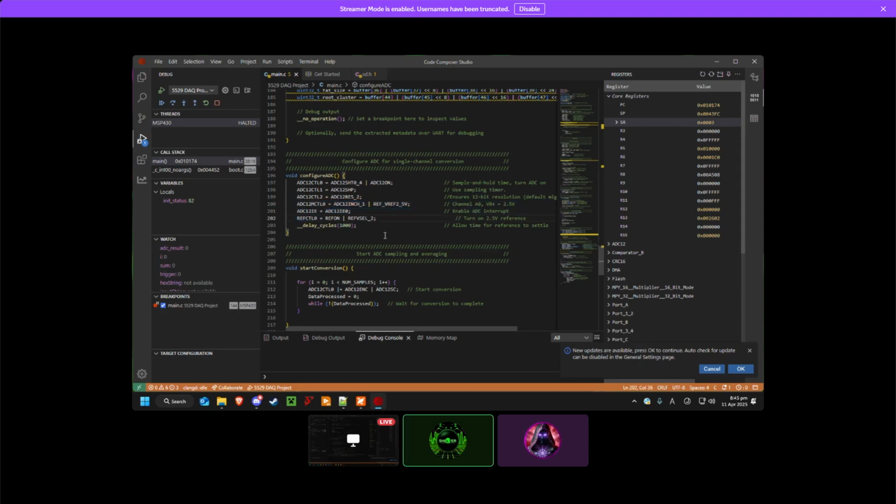We set the interrupt enable, so the ADC is allowed to interrupt the system. And then we set the, well, sorry, this is archaic. This is the archaic voltage reference set because there was an issue with my microcontroller unit having mismatched versions.